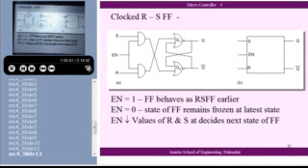Okay, I added to the confusion here. I have done something more here. I told you I would like to exploit the flip-flop as much as possible. I have taken the basic flip-flop. I just added 2 AND gates here. I put a common input, which I call as an enable input. You understand? I have taken a common enable input for both of them.